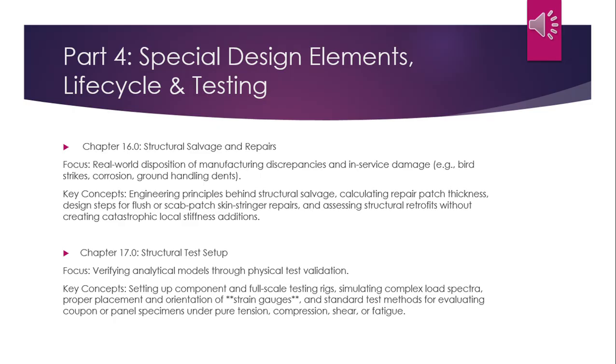Chapter 17 is about structural test setup. So it's about verifying analytical models through physical test validation. The key concepts is about setting up component and full-scale testing rigs, simulating complex load spectra, proper placement and orientation of strain gauges, and standard test methods for evaluating coupon or panel specimens, like the éprouvettes, and pure tension, compression, shear, or fatigue.